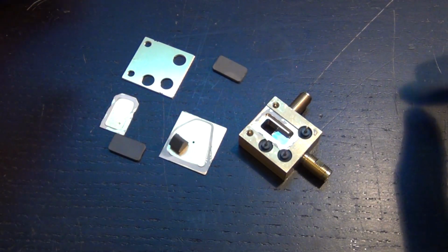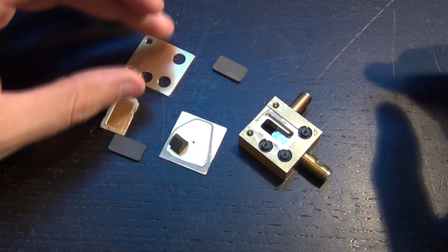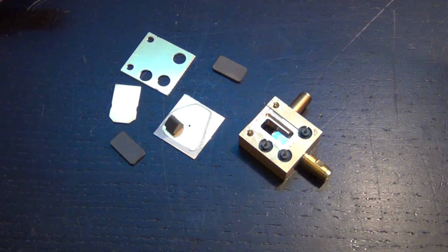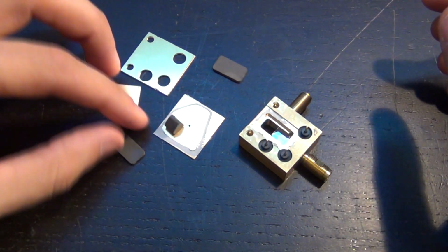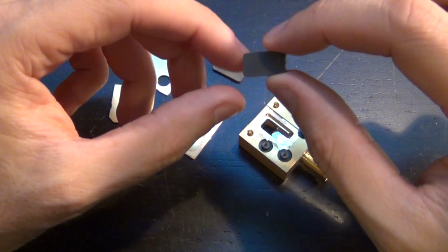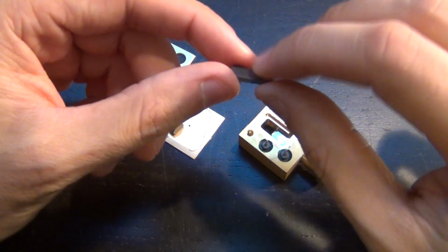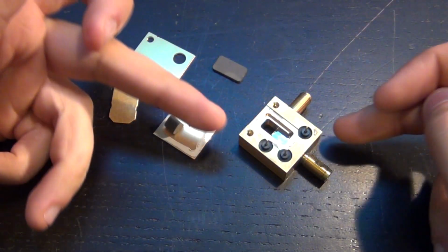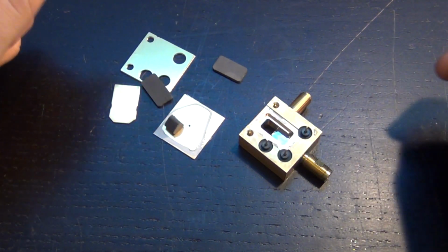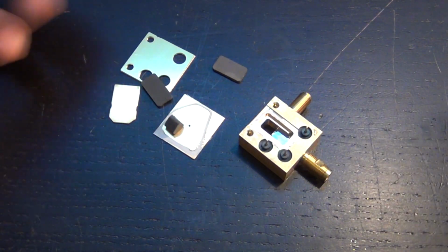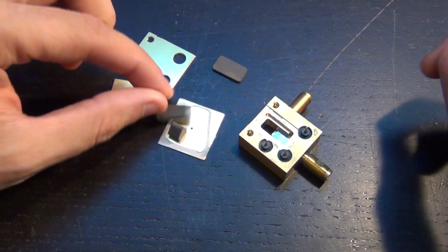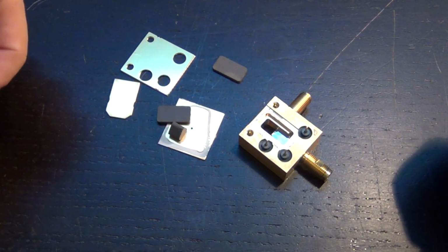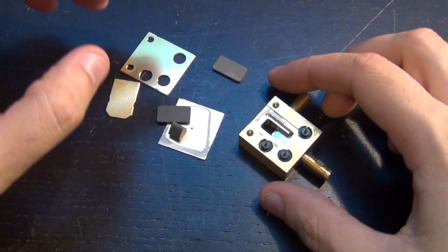So let's start from the sampler module. I've taken the cap off, the cover at the back and the front. These are glued in because they're assembled obviously by hand, one at a time. And there's a whole bunch of RF absorbers that we've seen before, I've talked about it before. They put these RF absorbers in various locations in the module because the chassis is all metallic, and you don't want internal reflections and internal cavity effects to take place. So by putting these absorbers all around, you contain all the EM field within it, and you prevent it from bouncing around the walls of the module in an unwanted way.